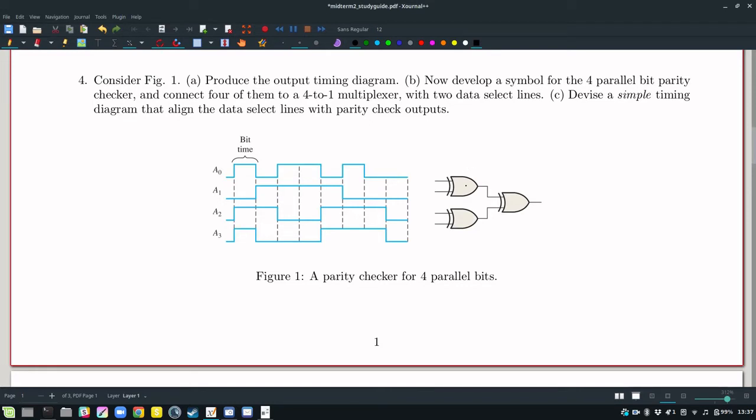So if you have an XOR gate, that's making sure that the bits here are different. And so these would be true, both true, so you'd have 1 1, but then the XOR would say false there. So notice that you have some number of ones, so 1 and 1, so there's an even number of ones and you get a 0. But if we change even 1 bit, then let's say that's a 1 there, then that's still a 1, but then the 1 1 in the lower XOR gate makes a 0 here, and that becomes a 1. And so this is true for an odd number of ones.